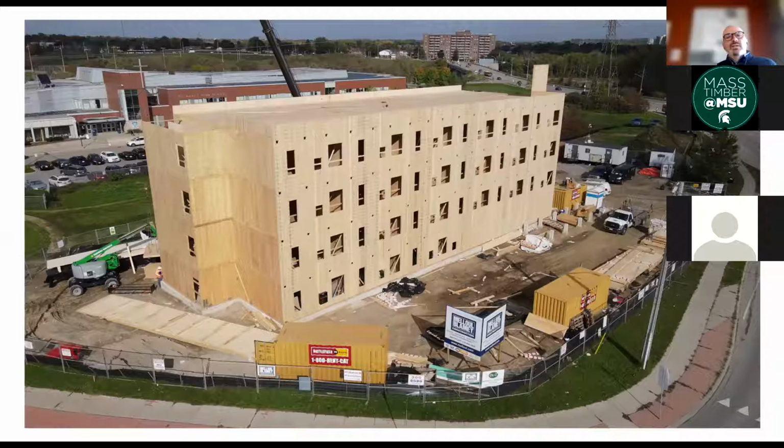So this is the YW project in construction. This is about a 25,000 square foot building. It's a 41 unit design. It uses the structure that I've indicated previously. You'll notice the panels on the left-hand side, they're horizontal. Those are structural panels on the shorter ends of the building, because those panels actually support the CLT slabs at each floor level. But the panels that you see on the longer walls of the building, those are non-structural.